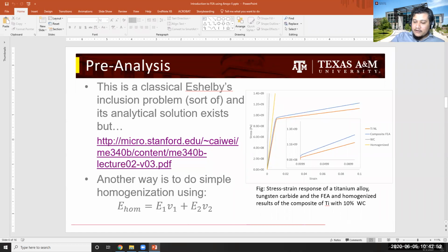Will we account for grain orientation? The material properties which we'll be using are going to be isotropic in nature. We are not taking care of any kind of anisotropy, either in the elastic part or the plastic part. So we don't have to worry about the orientation and stuff. No. Because grain orientation starts to be important only in the case where we have anisotropic properties, but I won't be using those kind of properties.